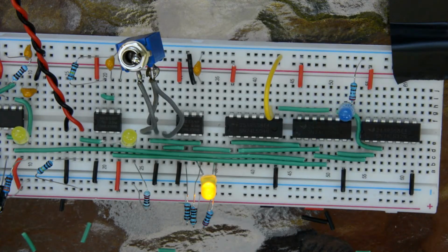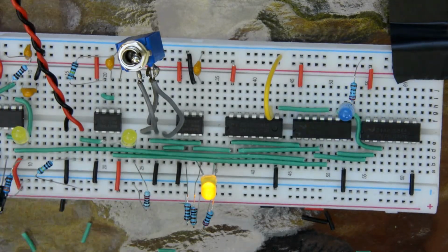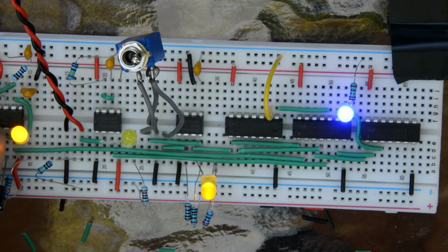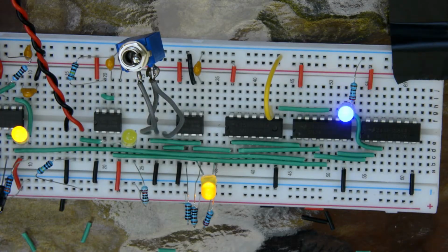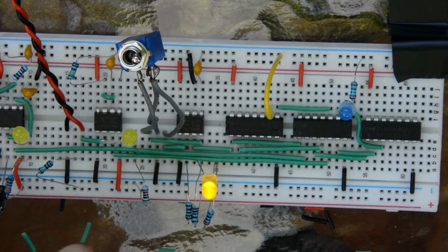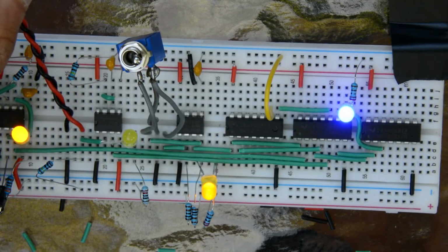Okay, so this is Ben Eater's clock module. It has a couple of things. There's 3 555 timers that are all sort of used in a different way. The first one is used in an astable configuration where it basically turns high and low in a set interval that can be modulated, so I can turn up or slow down the clock. The second mode is a button where I can manually turn something on and off.